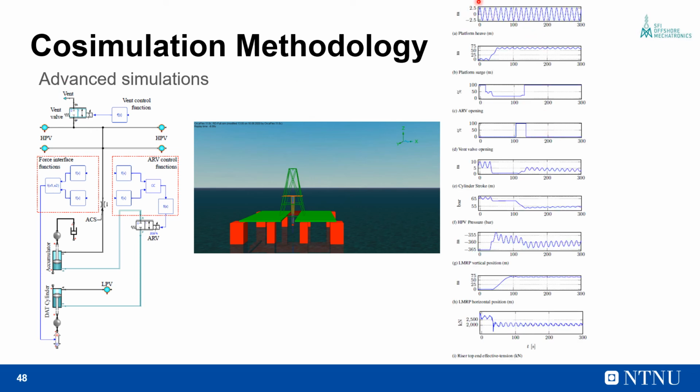Here we see that the platform begins to pull away from the wellhead at 20 seconds, and immediately after the platform begins to pull away, the riser is disconnected. The LMRP begins to rise as the riser is disconnected and the tensioner cylinder begins to retract. As the tensioner cylinder reaches a low stroke value, it is locked in position to prevent the riser from dropping down and the LMRP from interfering with the BOP.